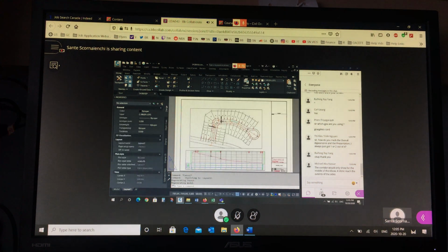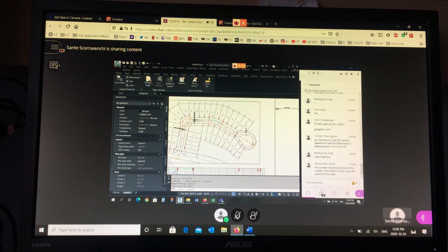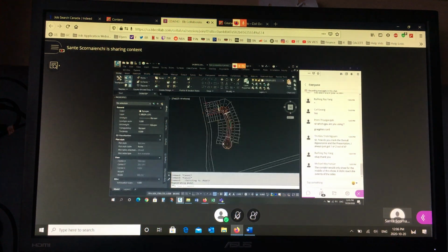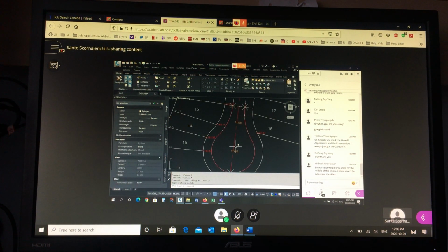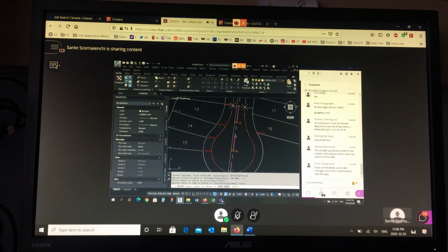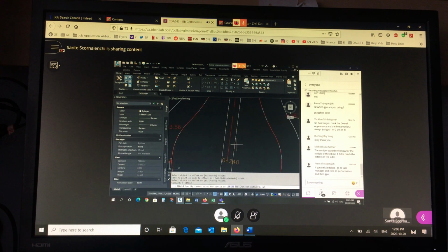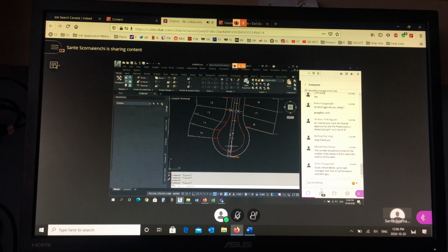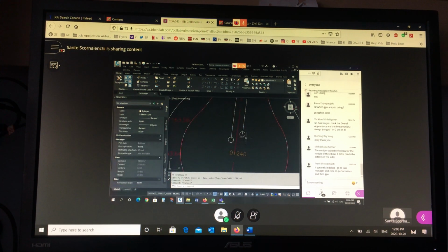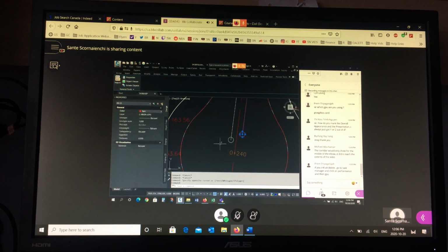If you go to the layout, the legend, when you're drawing your sewers, right? So if I suggest something here, right? If I draw my, if I offset by 1.5, right? Offset 1.5, and I draw a circle near of 0.75 and 0.75. If that's the size, then you want to have the same size in the legend. Right? So if that's what it looks like, let me just color code these. I think this was the sanitary. This was the storm on my drawing. I can't remember. Just as an example.